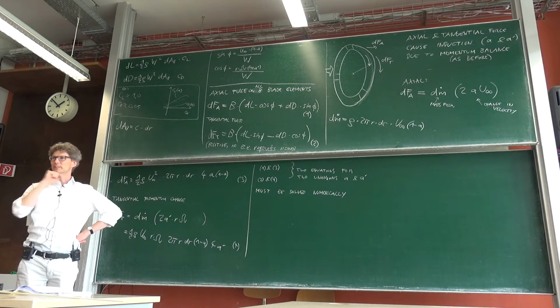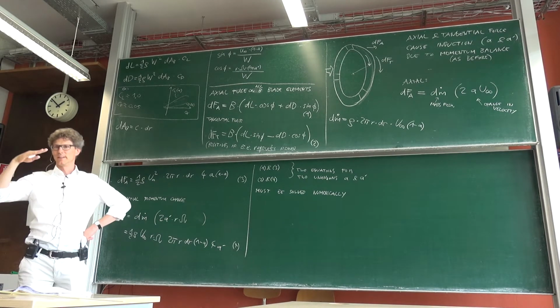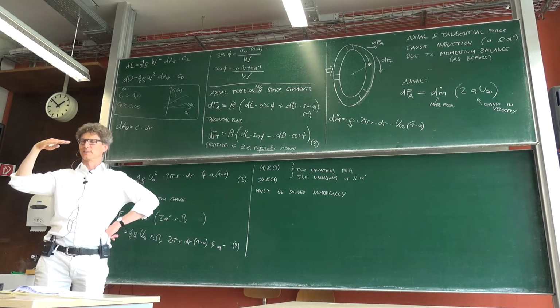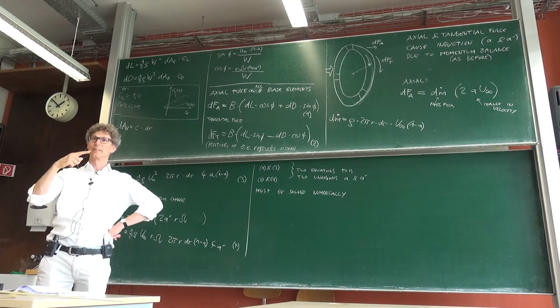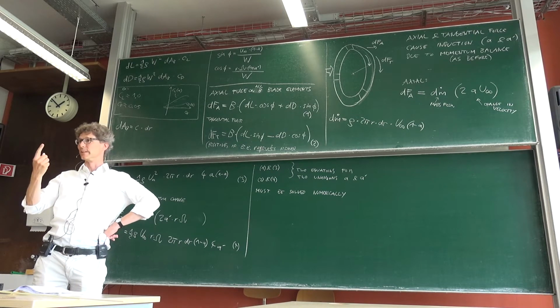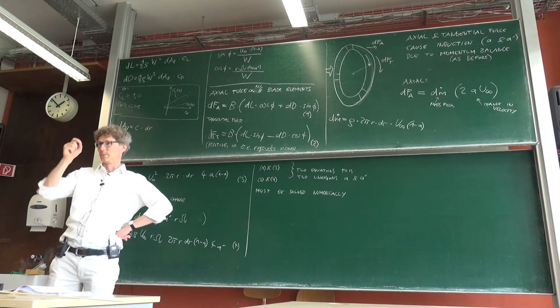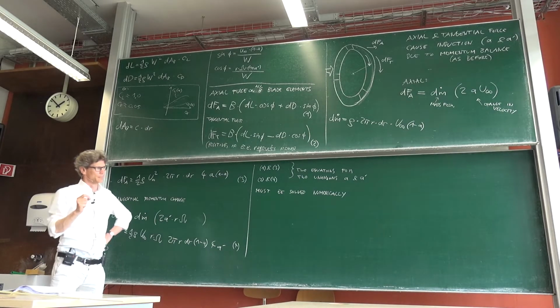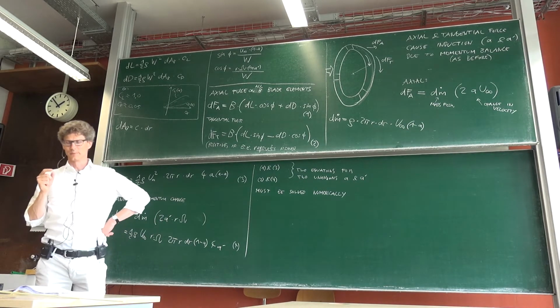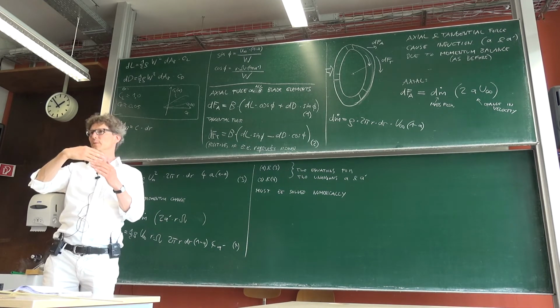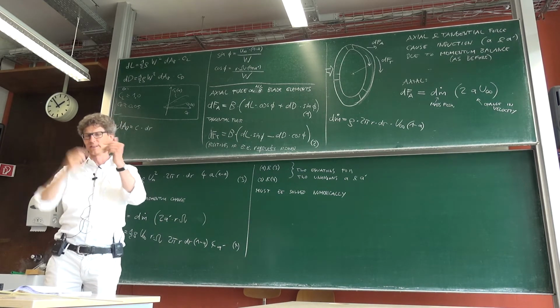And if you remember our geometry at the beginning, even the angle of attack and therefore also the lift and the drag coefficients, they would all depend on our a and a prime, right? So we would also need to include them. But what you can do to simplify your analysis is you just assume, and then afterwards you compute what will be your best angles.